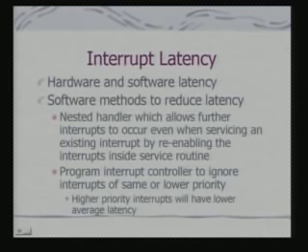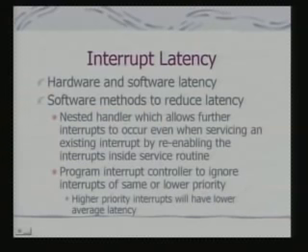So what happens? If I have an IRQ handler, inside the IRQ handler, I enable the IRQ bit. An interrupt controller is associated with priorities of the external devices. Now, if an external device raises an interrupt and this device has a higher priority than the device whose interrupt is being serviced, my interrupt controller will generate another IRQ interrupt request.